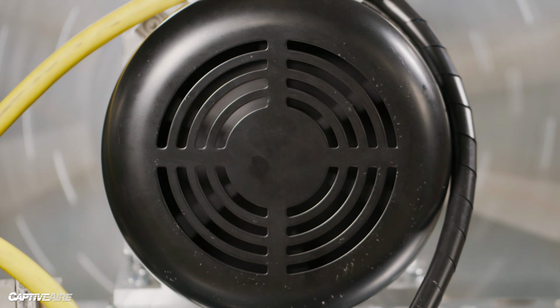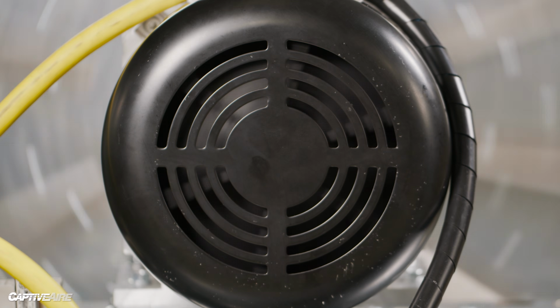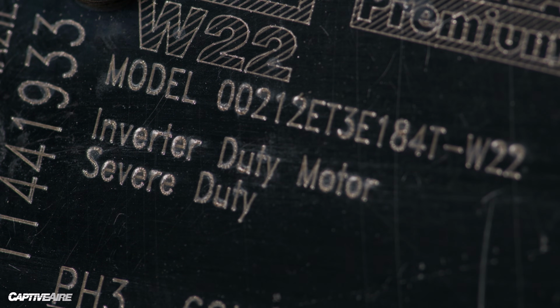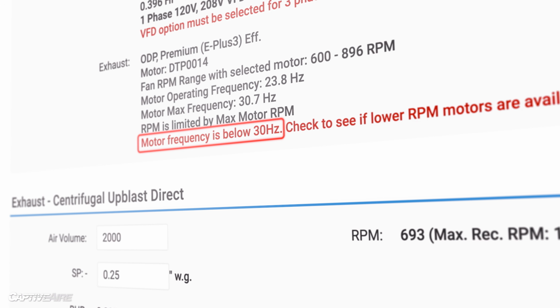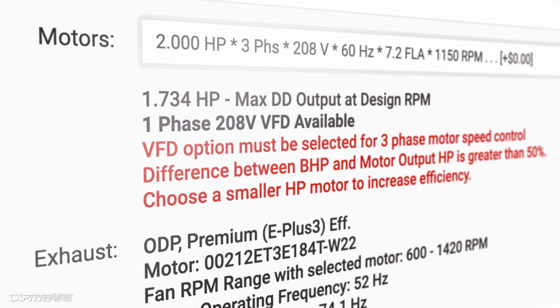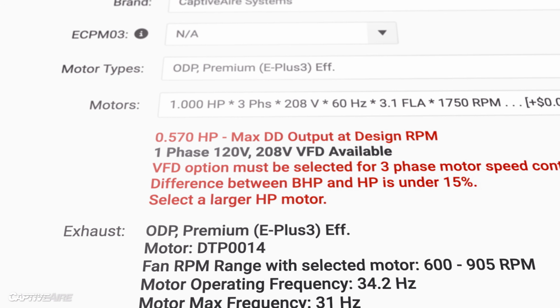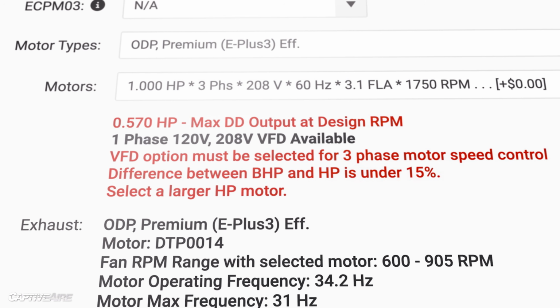converge. Furthermore, we don't like to slow motors too much because then we also start to lose some of the cooling across the stator coils. Inverter duty motors are better equipped to handle these lower speeds, but by setting limits on both the minimum speed and the percent load on the motor, we ensure that we use that motor within or pretty close to its peak efficiency and with appropriate cooling.